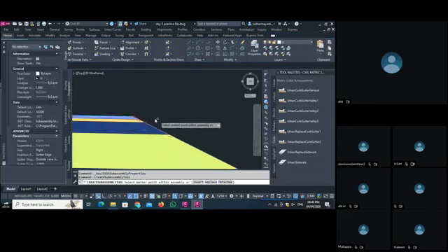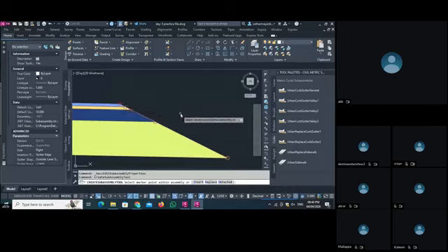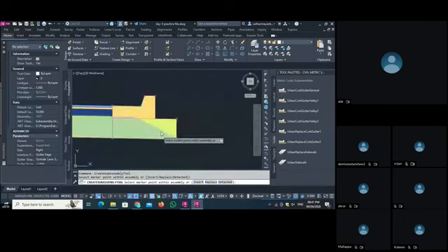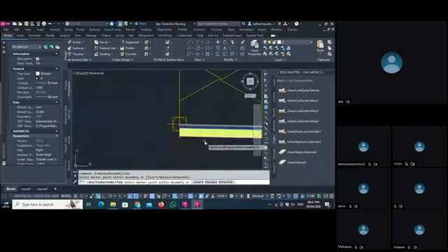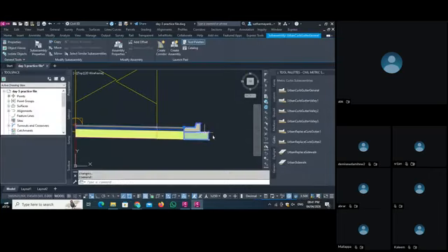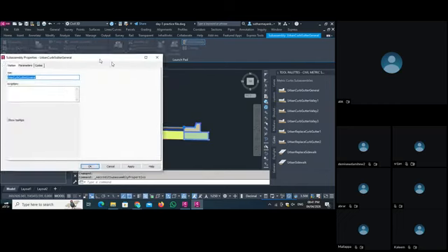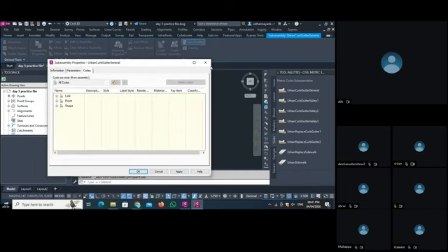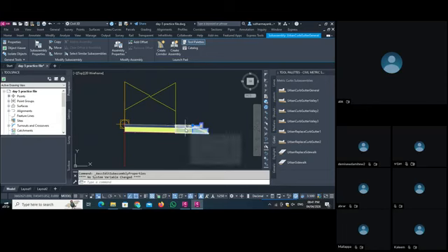Take this curb and see. As I said, you have to put it on the top only. Even though we have a different layer here, we use this top only. As we click here, you see our curb is created. Now the next thing I want to show: we go to this curb and check the sub-assembly property for this curb. You can change the name and the parameters, you see slope and all those things. We set and check all those things first, then we go further.